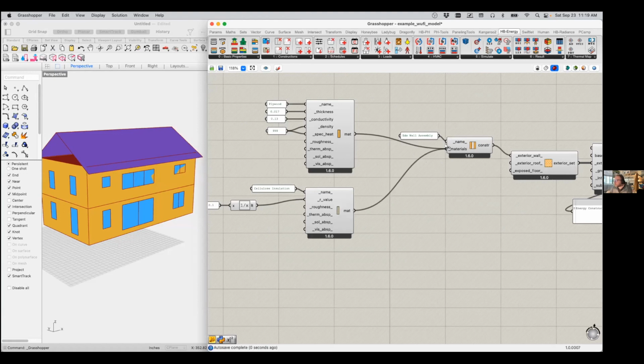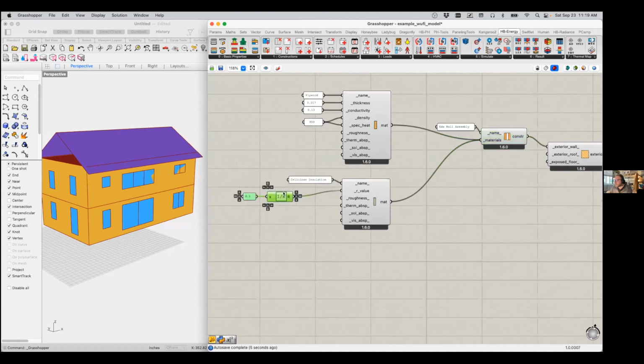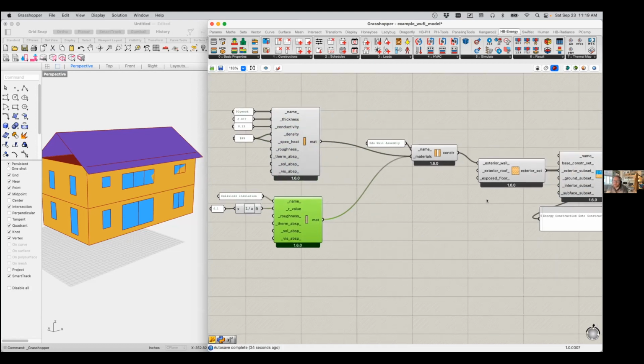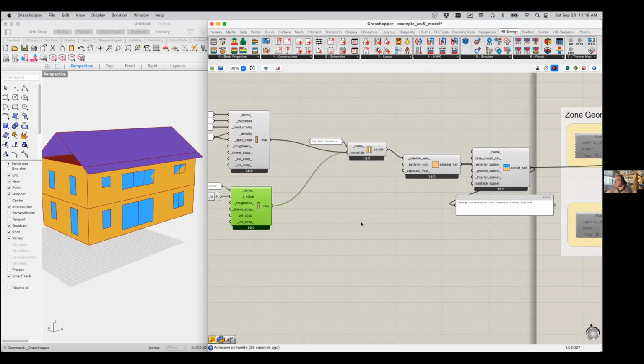So we've now got two materials flowing in. We've got an insulation layer and we've got a plywood layer. So we use a couple different components there. This one here asked us to specify all sorts of elements, asked us to put conductivity and thickness. This one's asking us just to put the R value. So different components that we might use in all sorts of different ways. I'm going to show you an easier way to do this, I promise. But this is maybe the standard Honeybee way.